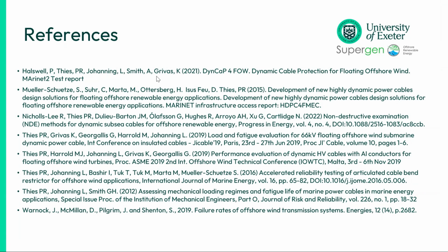Yeah, on the export cable side, you could argue the way they're installed is well known. The challenge is that for the subsea cables, as the arrays grow, the voltage levels go up. The voltage level has increased from 66 kV, and they're now looking at 132 kV designs. So already you're introducing some innovation to a new type of cable, and you need to requalify all of that.